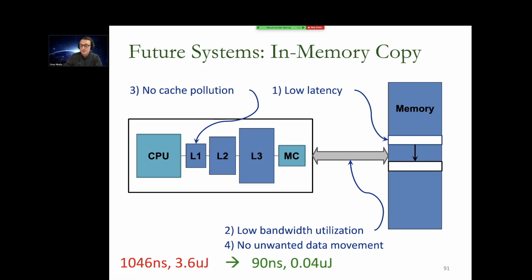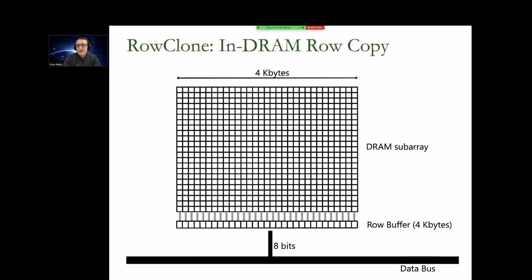If you optimize it, you can do even better, I think. And the idea is very simple. Once you recognize what's going on, and I think once you know the internal DRAM microarchitecture, we call this idea RowClone. It's relatively old right now. But the basic idea is if the two pages or rows are in the same subarray, which means that they share the sense amplifiers, row buffer, you can do this copy by doing 2 consecutive activates.